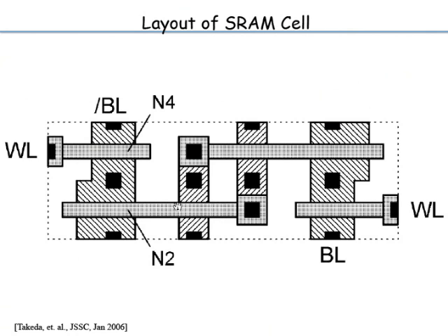This is the gate. So remember, the PMOS and the NMOS. So that is what is happening. You have source and drain, source and drain. Now, if you see from here, the drain, this is the access device, because the inverter's lower NMOS transistor is the driver device. And the driver is connected to the access. So that is done just by extending this diffusion, and then you have the word line here, so this becomes the access. These blacks are the contacts.